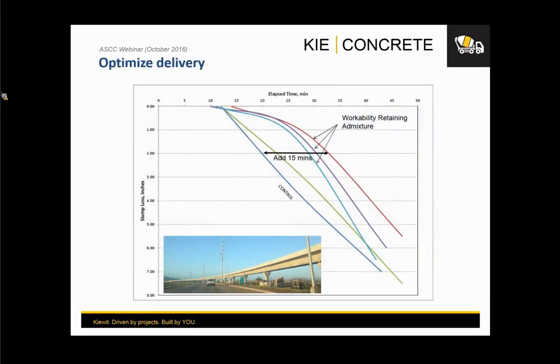And thinking about it, this was interesting. This was a case where we had a precast facility where we were building our own precast yard, and we had set up a batch plant too. And in precast, obviously, you would not consider extending the workability of the concrete, but in this case, we needed to achieve a very high early age strength, and the mix was so difficult that in 10-15 minutes, you were losing the mix. You were getting the mix really stiff, and then it was getting really difficult to vibrate and consolidate, and was creating bug holes.